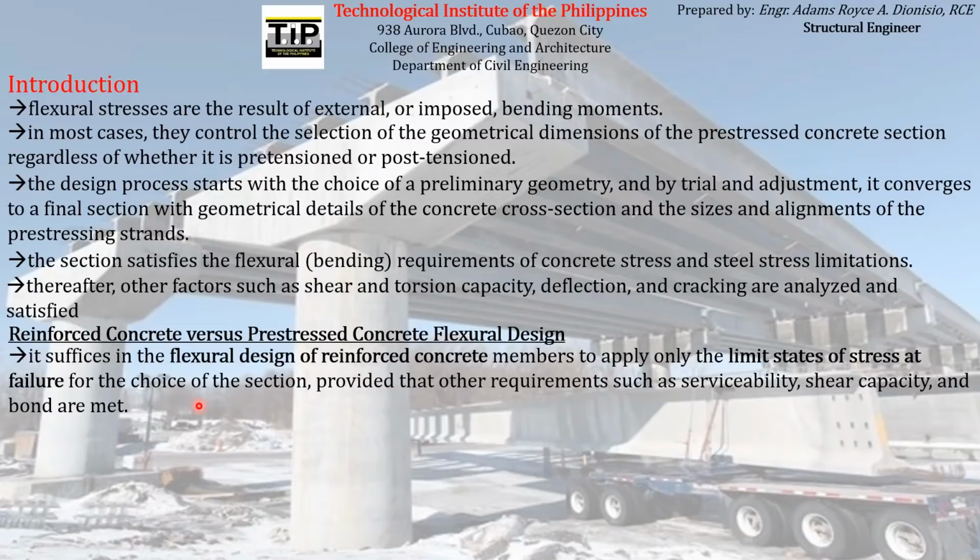the reinforced concrete will already experience cracking and impending failure, meaning total failure, as in the flexural member may already disintegrate, although we can actually say that failure already occurred if the steel reinforcements of a reinforced concrete already yield, as well as the concrete itself.